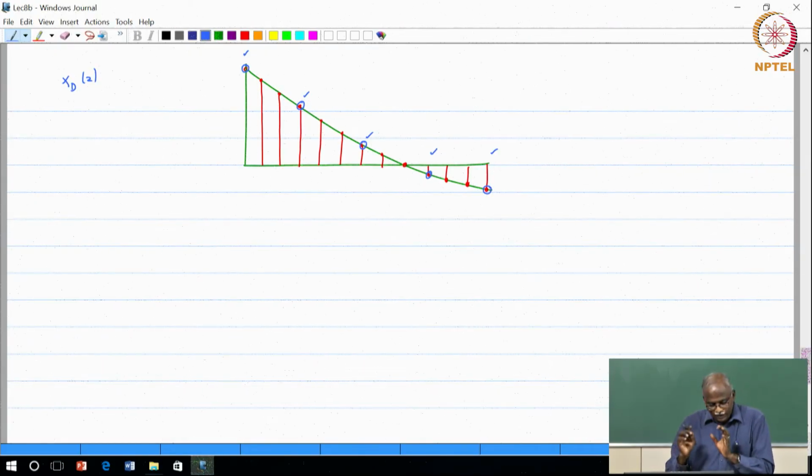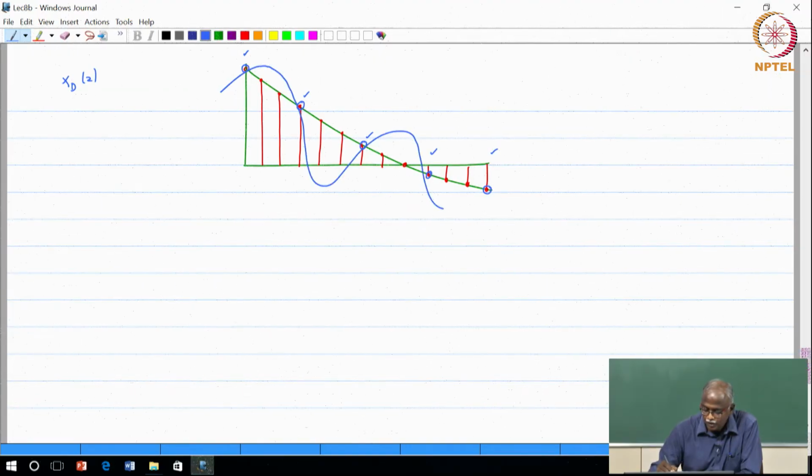Now, here is the example and its illustration. Just as a case study, if I had a continuous time signal given by this blue graph and it had been sampled, I would have gotten the same samples as if I had the green line and sampled it at this rate. Now, when I am given only the samples and asked to reconstruct, what I am most likely to reconstruct is something that looks like the green line, because I do not have enough information to reconstruct the blue line.